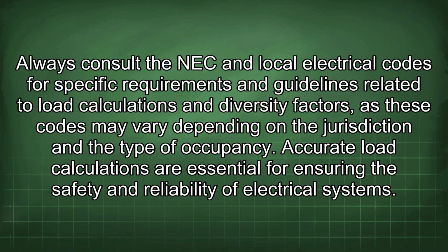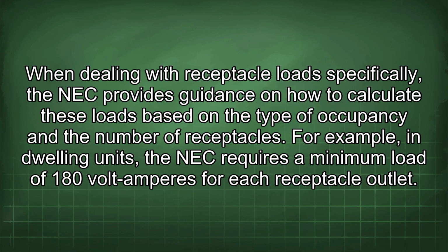Accurate load calculations are essential for ensuring the safety and reliability of electrical systems. When dealing with receptacle loads specifically, the NEC provides guidance on how to calculate these loads based on the type of occupancy and the number of receptacles. For example, in dwelling units, the NEC requires a minimum load of 180 volt amperes for each receptacle outlet.